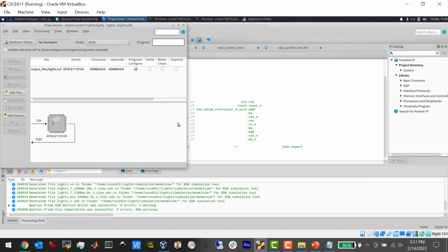If you wanted to permanently alter the soft file that's on the flash chip, then you still do it through JTAG, but you have to change the JTAG chain configuration. For whatever reason, they don't have the FPGA and the flash chip on the same chain. I don't know why they didn't do that. But anyway, there's TDI and TDO. Any questions about that?